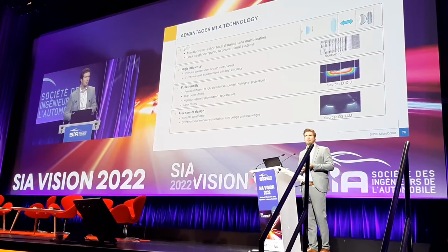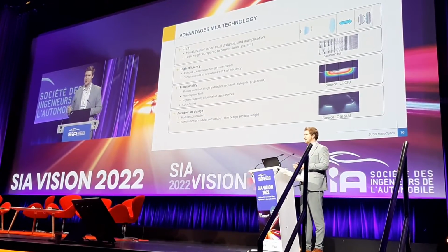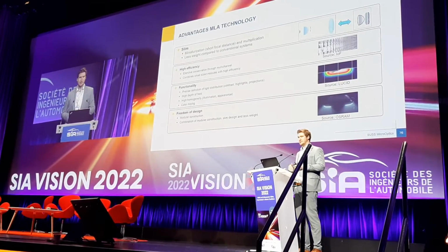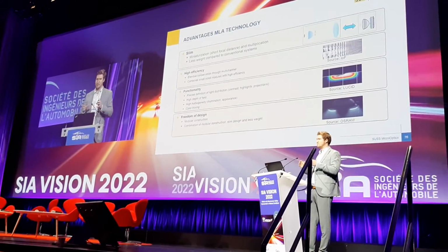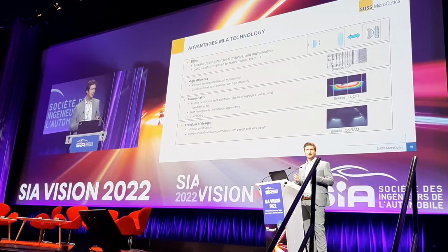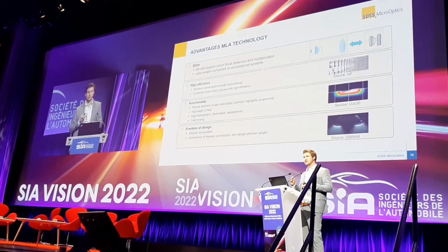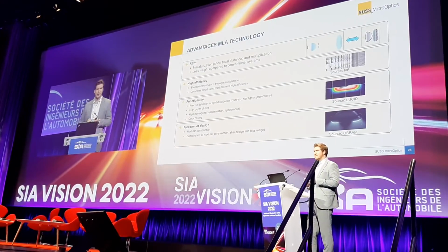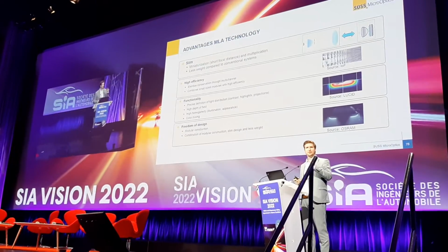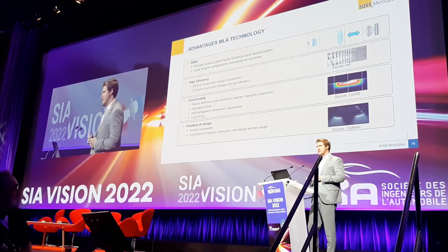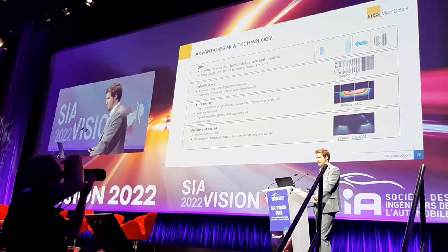Then there's more functionality, because we have several hundred lenses in headlamps, up to 1,000 lenses. This gives different advantages. One advantage is that each lens is illuminating the full field, so the overlay gives a very precise and homogeneous appearance because it's from different lenses and not just one. And for each lens there can be a slightly different design, slightly different grayscale. So a lot of different possibilities to shape the light in the ways you'd like.